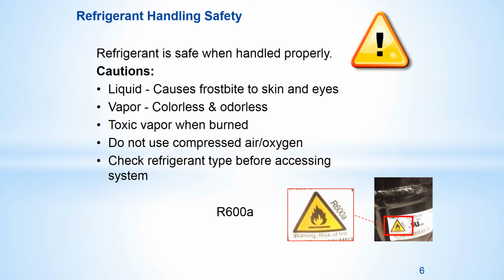Do not enter the R600A seal system unless you have been trained to do so. For flammable refrigerants such as R600A, technicians are required to follow Sears approved procedures for recovery and disposal. Do not mix refrigerants in the product or service equipment. Mixed refrigerant in a returned recovery cylinder has to be destroyed at significant cost to the company.